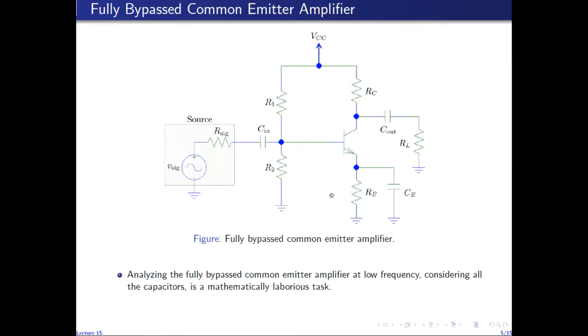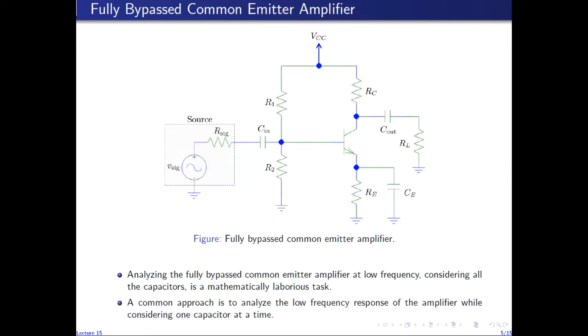But now we will be analyzing this circuit at the low frequencies, in which we cannot ignore these coupling capacitors, as well as the bypass capacitors anymore. However, analysis of this circuit, considering all the capacitors, is a mathematically challenging task, which is why a common and approximate approach is to analyze the amplifier at low frequencies by considering one capacitor at a time.